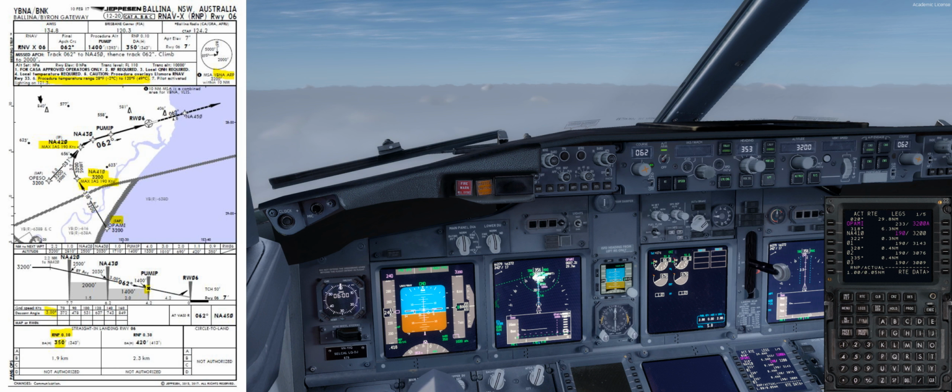There is a 36-page training presentation that you can find for VOS members on the website, and we're using the proprietary Ballina nav data for this approach. The main differences between the RNP LNAV/VNAV approach and this RNP approach is that this procedure utilises actual RNP capability. There are smaller tracking tolerances laterally.